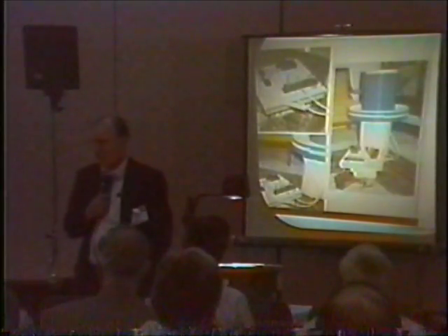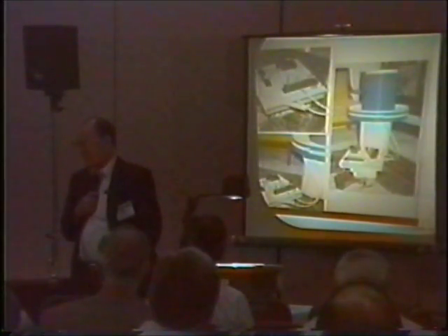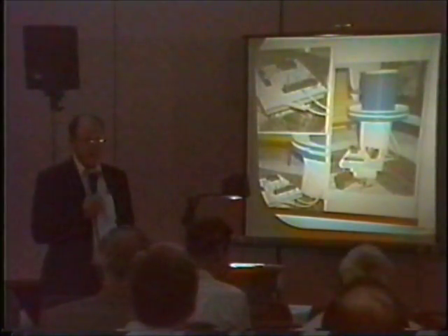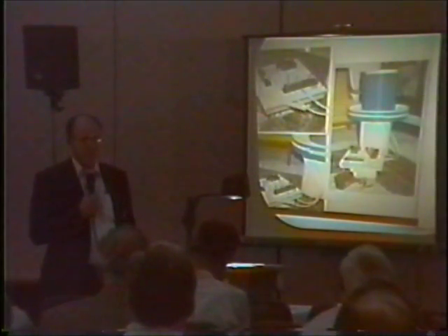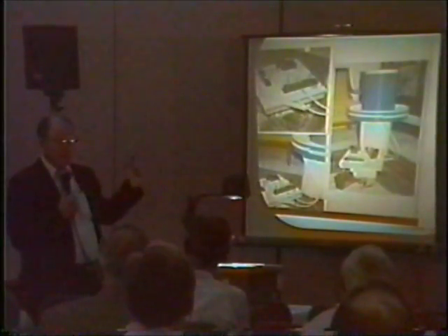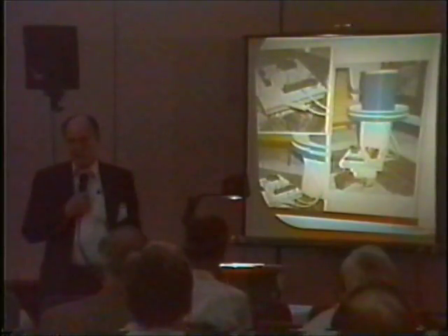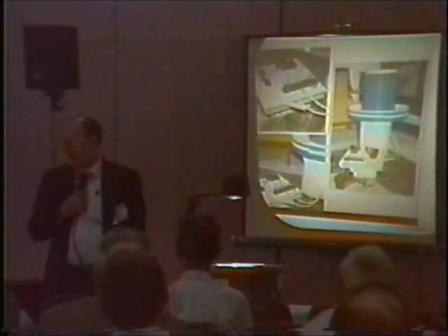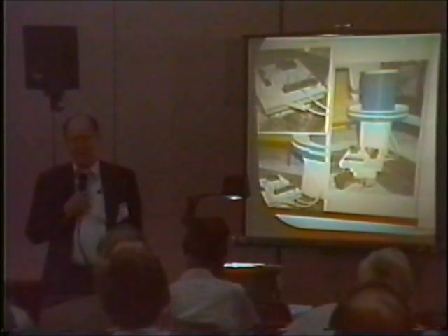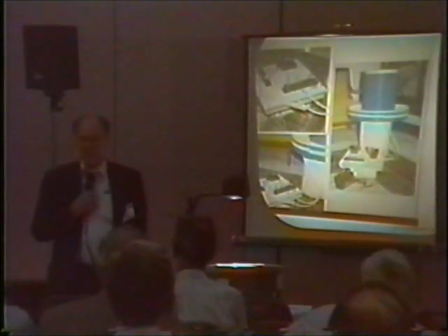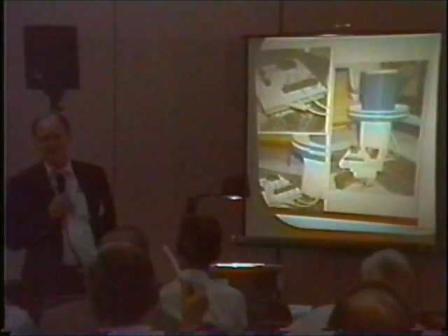This one was supposed to have come out 400,000 volts at a fairly high cycles per second sort of thing. And whenever I got it built, it turned out that the capacitance by the large diameter and the capacitance between those wires, it came out with a natural frequency of 400 cycles per second, which a while ago I was mentioning that it's possible to build these coils so that they will run down in the range where you can get electric motors that are set for that particular cycles per second.